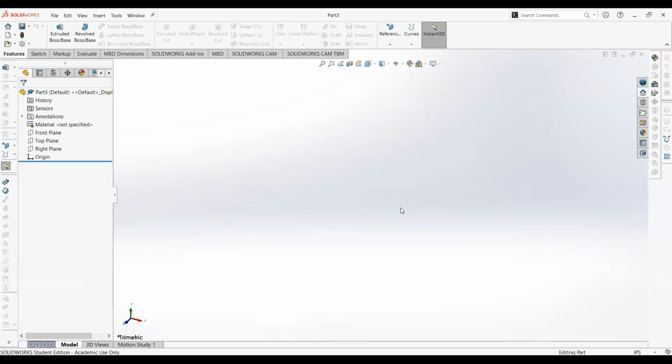Yes? All right. So a couple of things about SolidWorks first, addressing some of the very common mistakes that I see, especially last semester when I was helping out with this. In SolidWorks, a lot of people have this tendency to try and click and drag, and that's not going to work. You need to click and release, then drag, and then click again to anchor. Everyone got it? So click, release, drag, click again. Otherwise, it will not work, and you'll be sitting there trying to figure it out.